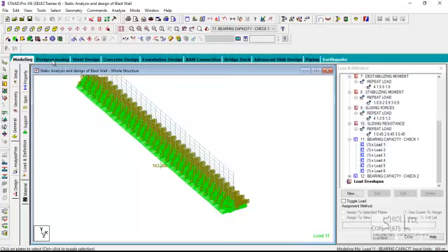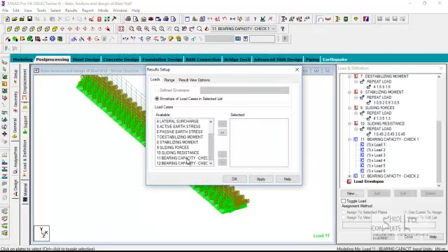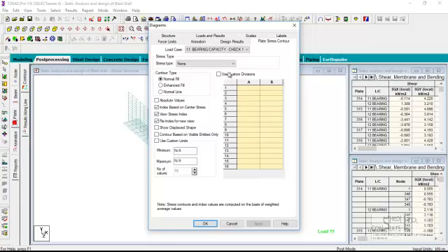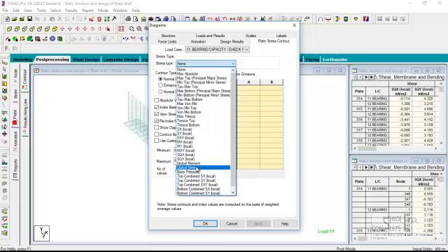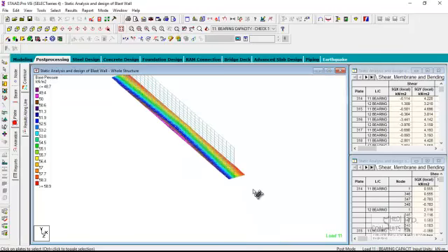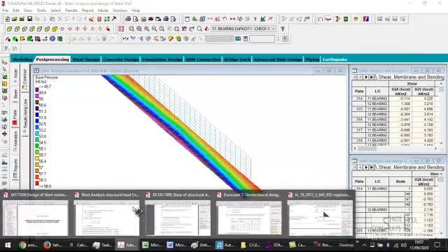So at the completion of the static analysis, let's look at the outcome. The maximum earth pressure we have is about 58.9, and that's quite less than the allowable bearing capacity of the soil, so we are very fine.